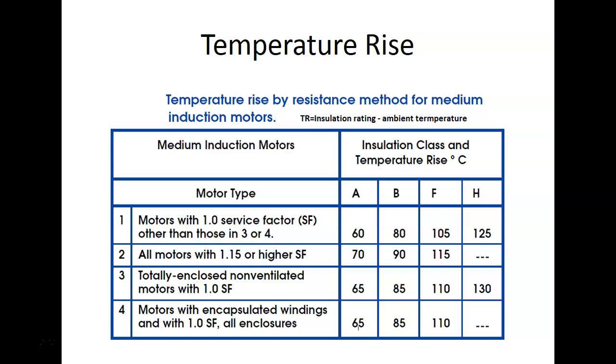All your high power capable transformers, they'll immerse them in oil, and they'll do a lot of oil. You'll see a lot of your substations where you can see your three big transformers out there, and each one of them has on the side a radiator, just like your car, and then they'll have a fan blowing on there, cooling that oil, trying to get the heat away from the transformer. No, because grease you can't move. So either they blow air on them, or if it's big ones, they'll actually put oil.